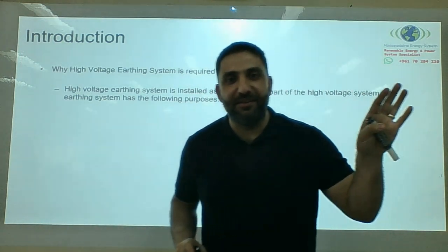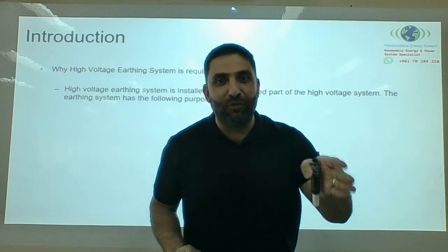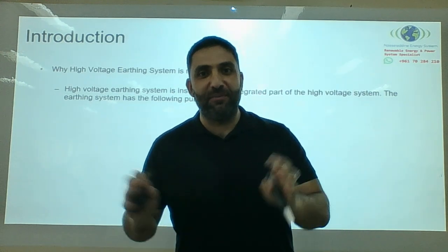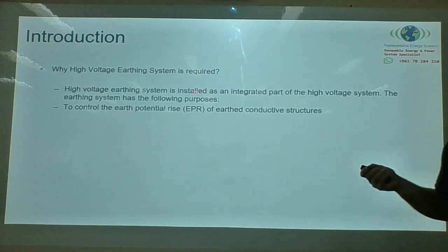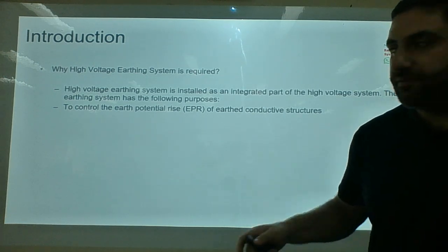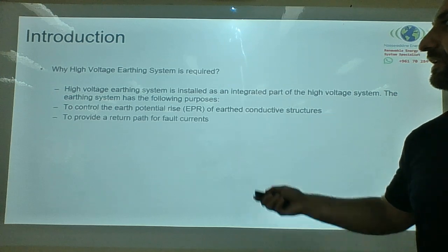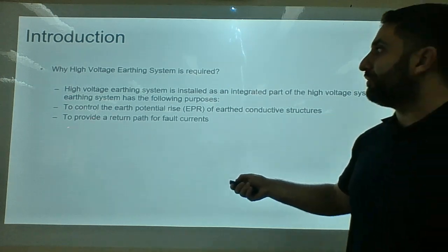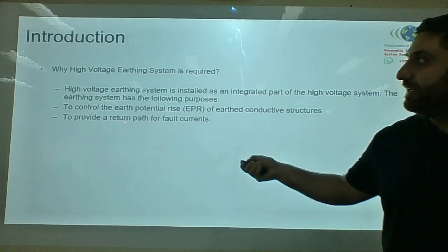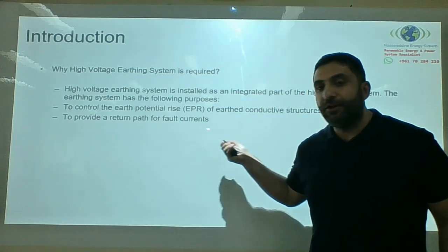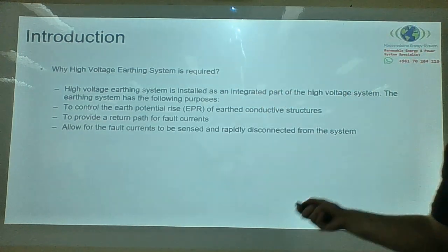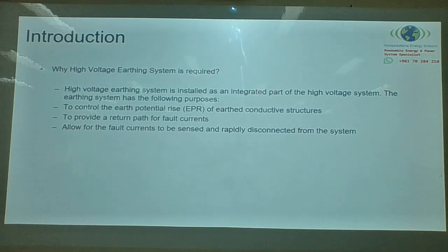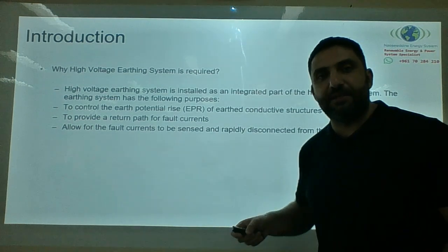There is no building that has a low voltage system or a high voltage system or a mix without having an earthing system. Because as we spoke, I need to control the EPR, the earth potential rise, to provide a return path for fault current, a safe return path for the fault current, for the fault current to be sensed and rapidly disconnected from the system.